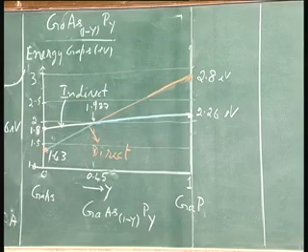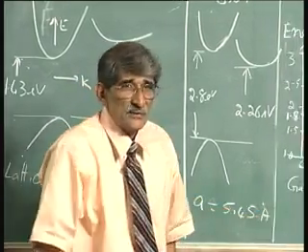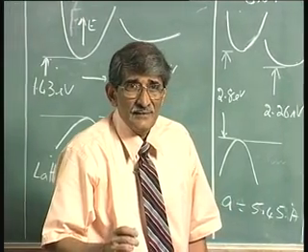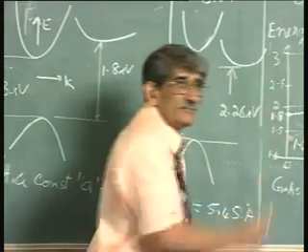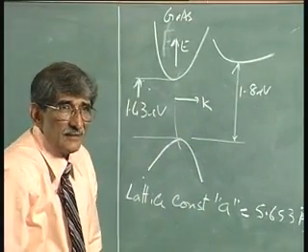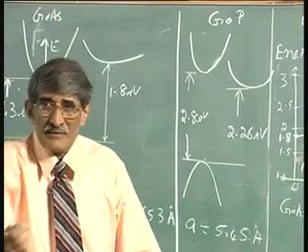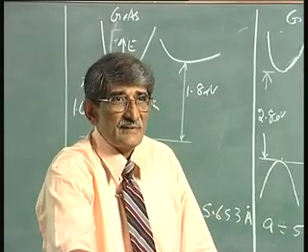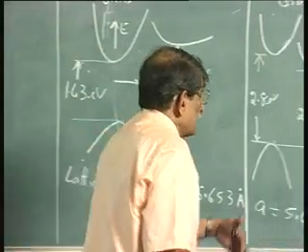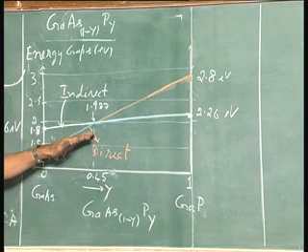If I want to make a light emitting diode, which portion of this diagram will we use? The answer will be immediate, because direct band gap. Direct band gap gives transition like that. Indirect band gap, transition like this will not emit light, because last time we mentioned it will be a two-step process, because of momentum difference. So, if there are no intermediate levels, it will be this portion which you choose.